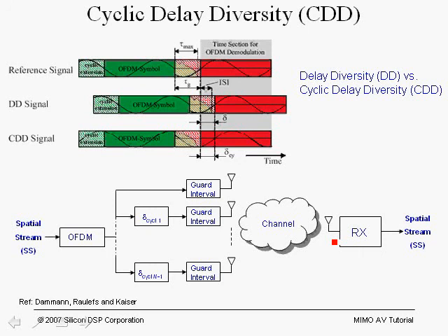We'd have a large peak to average ratio, and we can have some deep fades. However, by adding the cyclic delay, these two signals become somewhat decorrelated when they are added in the receive antenna, and this improves the performance and also adds a diversity gain.